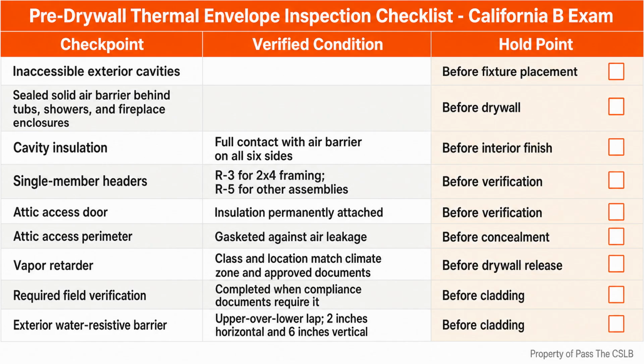If a proposed foam plastic product or wall layer differs from the approved assembly, resolve it before installation. If a vapor control decision requires hygrothermal analysis, send it to the qualified specialist. Good supervision includes knowing when the verified rule ends and project-specific design begins.